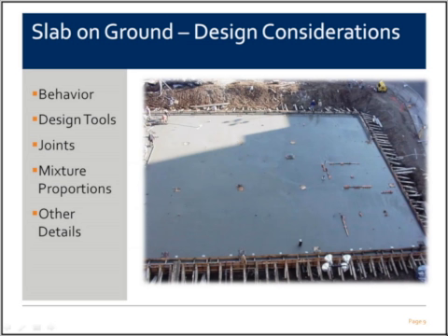I will be leading the first half of this presentation and will mostly focus on slab on ground behavior and design tools. Todd Nelson will talk about joints, mixture proportions, and other details that are considered in design. You may have noticed that we use the term slab on grade in the title, but we will refer to it as slab on ground because what we're really talking about is a slab built directly on the ground, which may or may not be at a grade level. ACI recently has been pushing for the slab on ground terminology instead of slab on grade, but they are interchangeable in a sense.